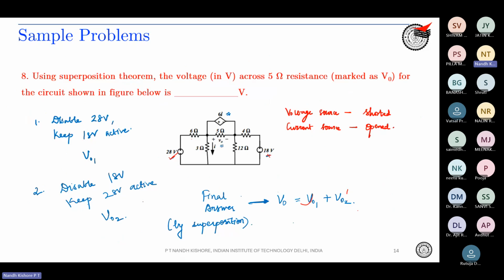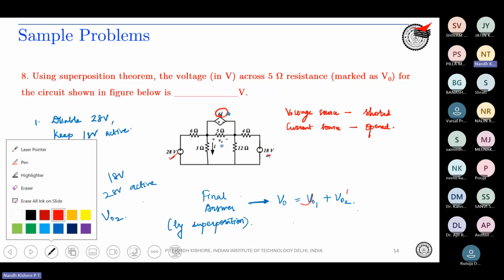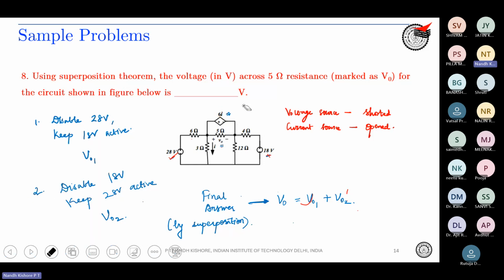Did you get how we did it, everyone? We applied superposition, but even after applying superposition, you have to make sure that you relate the parameter I with the equations you are writing in terms of I1, I2, I3, in this case because we applied mesh analysis. Similarly, if you did nodal analysis, you have to relate your I with whatever voltages you will be assuming.